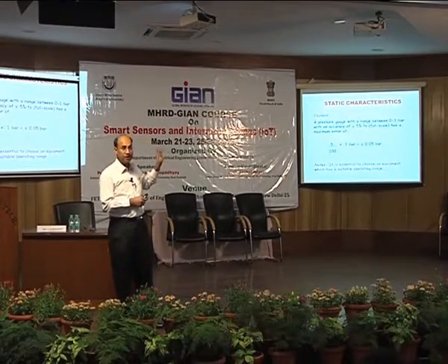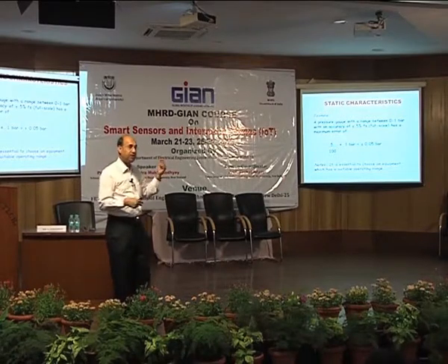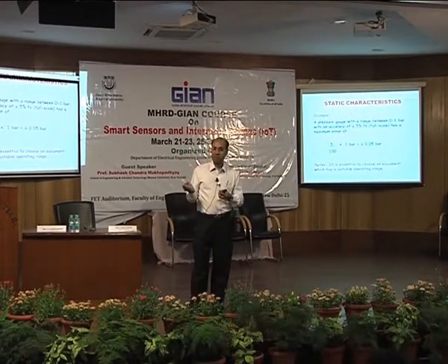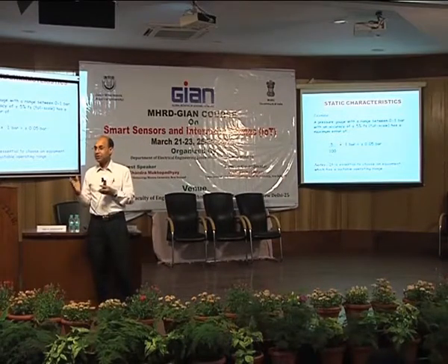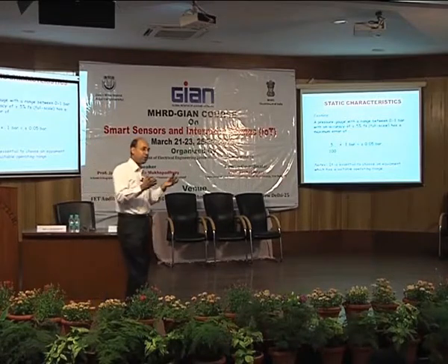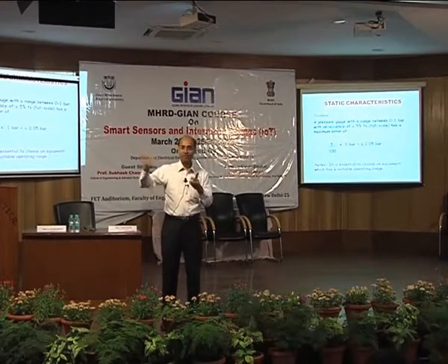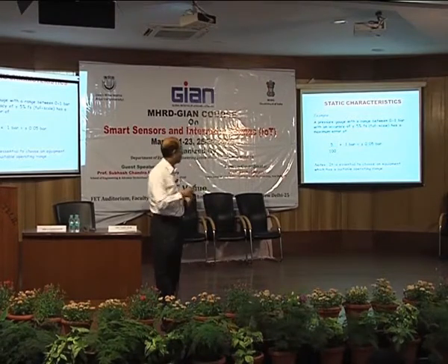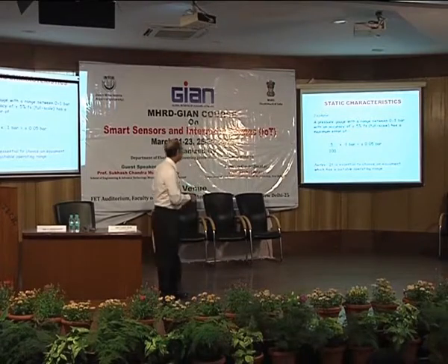It's clear, isn't it? So the accuracy is related to the scale. Sometimes you say its error is 0.1 degree centigrade, but that may not tell you the real picture, because you may have 0.1 degree centigrade be good in some applications, but not that good in some other applications. You understand? So the real value may not give the correct picture. So you need to see the percentage.